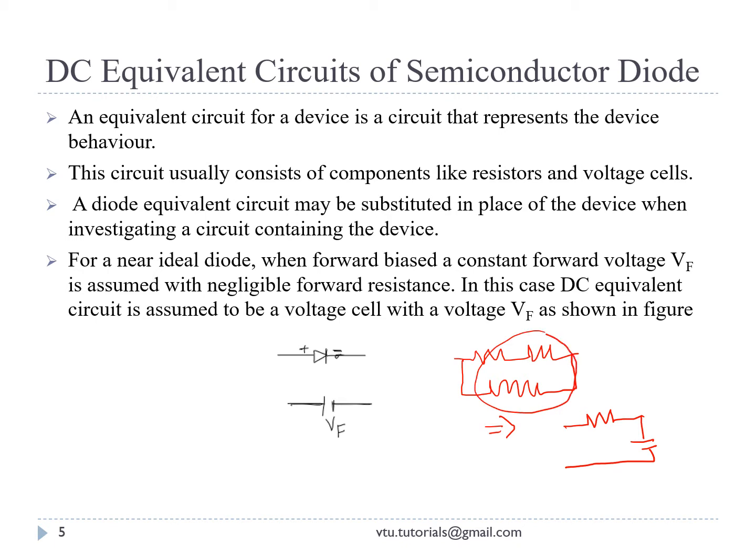In the same way for a diode, we already know its characteristics. When you consider a diode in any of its states, it is going to have one resistance for the flow of current and it can be represented with a voltage source. This is one of the model representations of a diode we have considered earlier.